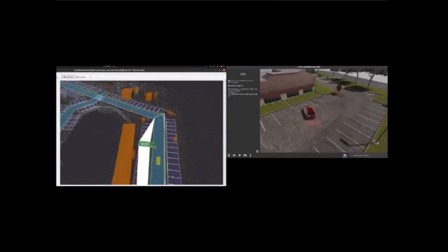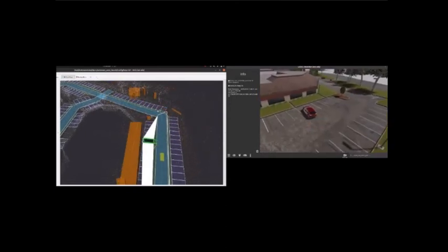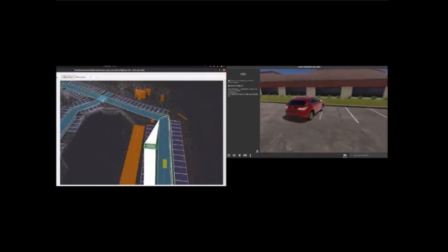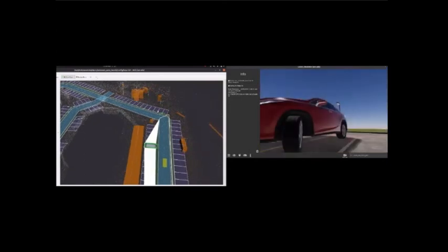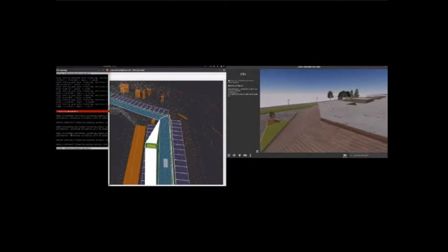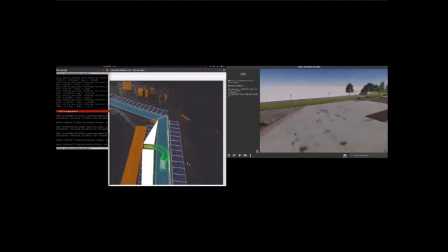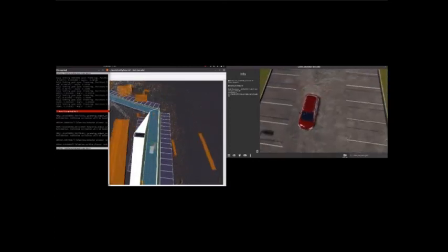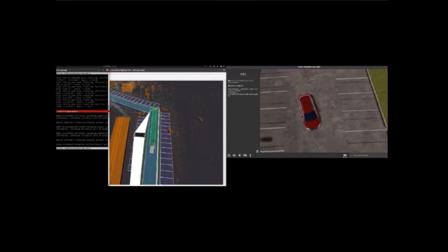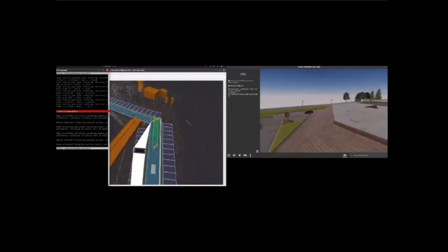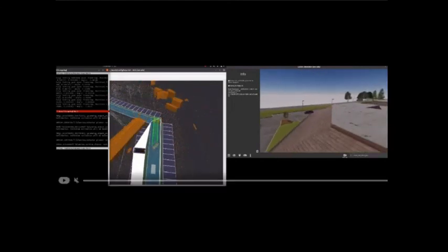Of course, this spot I selected programmatically, or in Rviz you can just select where you wish to park the car. And then you can also get out of the spot using the same planner, and then switch to the lane planner and the global planner again to find a new place to park the car, and so on.